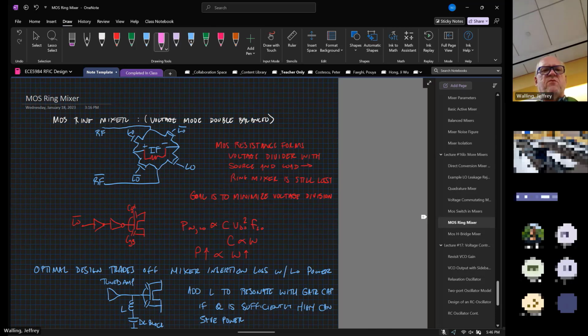And in fact, more recently, I'll share a paper. What we've done is added more phases. So here we have a 4-phase, we have a 2-phase, 2-path switch. What they've done is they've made it more like 8 phases with multiple paths through the switch. And if you arrange the paths correctly, you can cause harmonics to be canceled or do all kinds of different things.